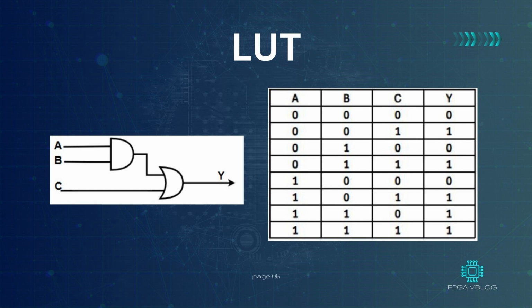It is a logic circuit with 3 inputs. So we can use a 3-input LUT with the values given in the table. Here, the input works as the address of the memory unit and output works as the stored element in each memory location. In such a way, LUT gives the correct output for the given inputs.